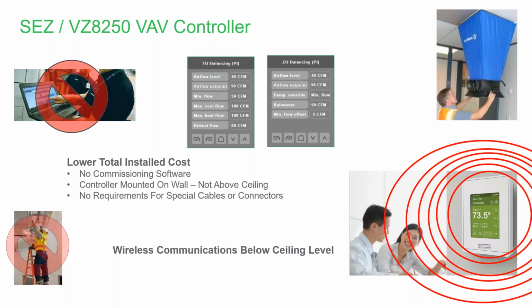But if you bring that into, let's just say, a Jace, pick your poison, whatever you use for that supervisory type control, you can bring those zones in. The 8250 is a zone. You do your system weighting, and then you tell the RTU to do something, heat or cool, and the zones operate in direct acting or reverse acting depending on what mode the system's operating in. So the short answer is yes, we have an RTU version.